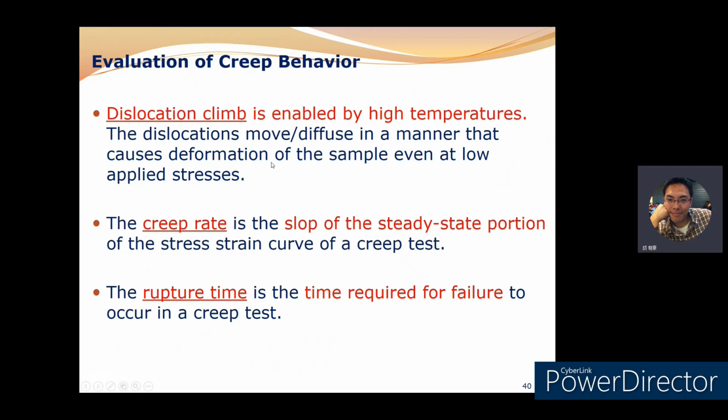So let's evaluate the creep behavior. Dislocation climb is enabled by high temperature. The dislocations move or diffuse in a manner that causes deformation of the sample even at low applied stress. So why is this dislocation climbing?